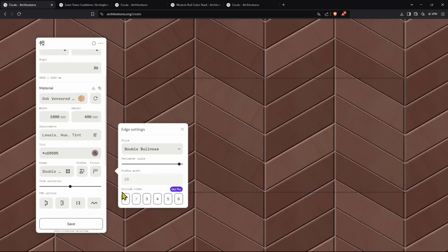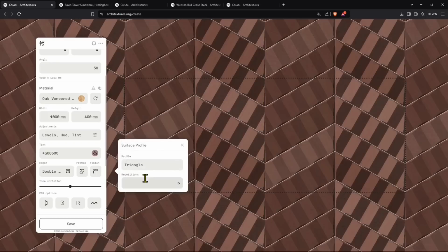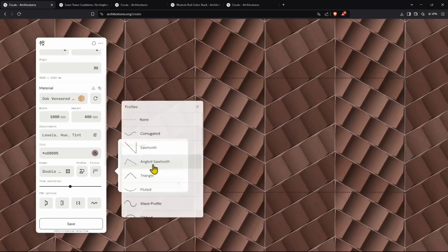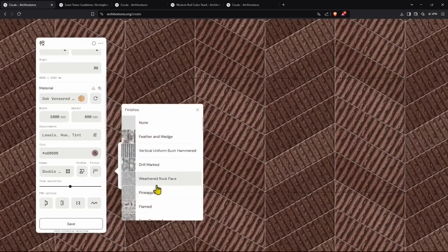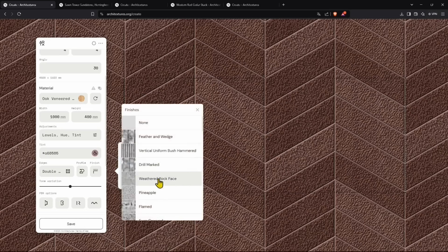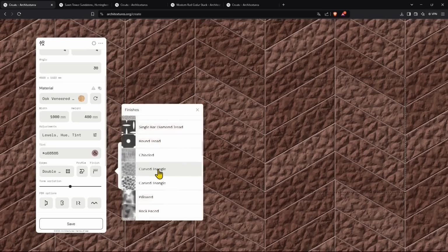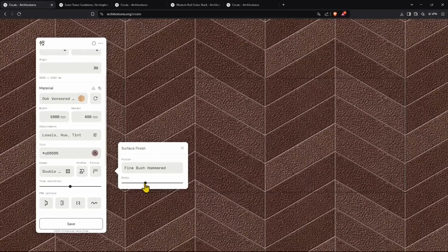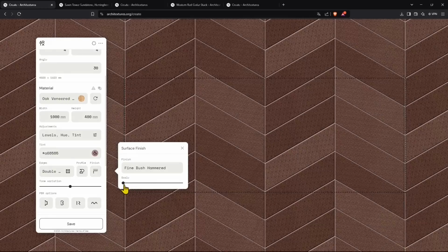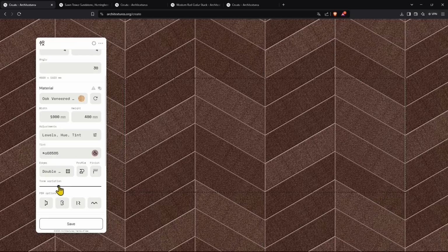And again, other pro features in here, and then you have surface profiles. So if you want to make like a roof or a strange wall, and then you have other finishes here, surface on the surface. These will appear especially if you use normal maps, displacements, bump maps. Again, superficial finishing. And you can change also the scale, so you can make it bigger and smaller. You can adjust your displacement or bump or normal map in the 3D software to make it more or less extruded. And then you have other stuff down here.